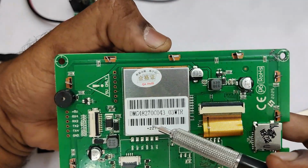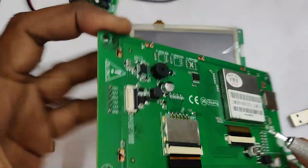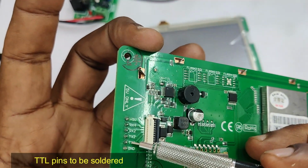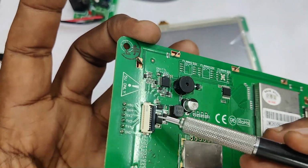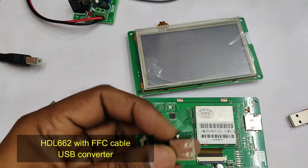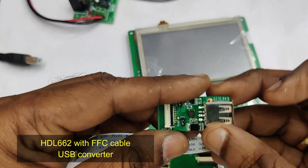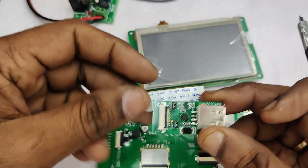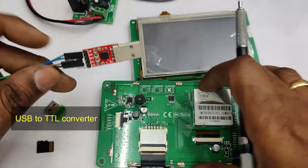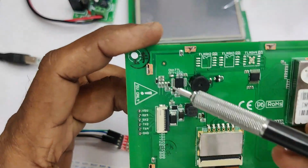This 48270 means 480 by 270 resolution, 4.3 inch, and the last letter R stands for resistive touch. You have to solder these 6 pins to interface with a microcontroller like Arduino. There is also a connector to fix the FFC cable, that is a flat flexible cable, and you have to use the official HDL662 USB to TTL converter. You can also use this USB to TTL converter made on CP2102, which is easily available in the market.